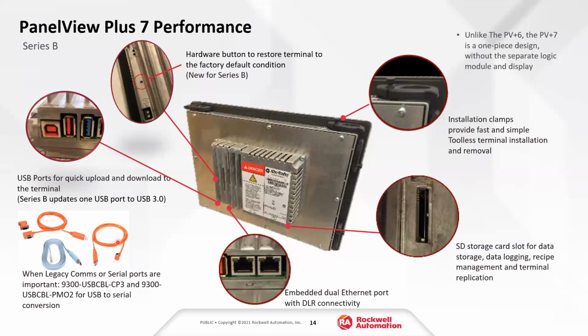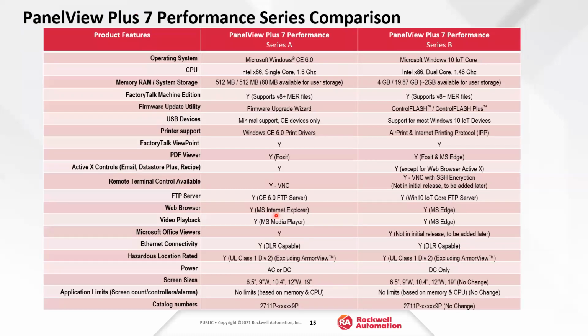If you're connecting to the MicroLogix or to an SLC 500, this blue cable is actually the console cable for a Stratix switch, so not something that you would plug in there. But that USB port can be used to do serial communications to those 2 controllers. Other than that, I don't think there's any other functionality that the USB port brings other than maybe plugging in a keyboard. You are correct. Good.